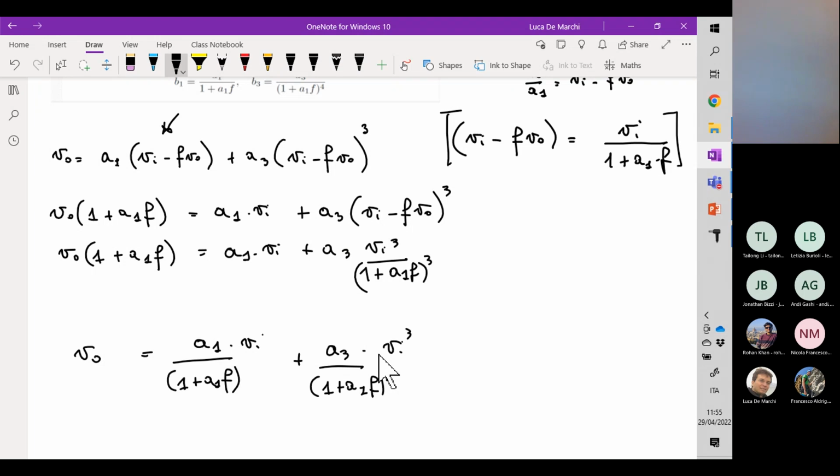We may have some different situations. For example, in this case, you see that when we are at gain equal to unity, loop gain equal to unity in modulus, the distance between the phase curve and the minus 180 degree one is relatively small.